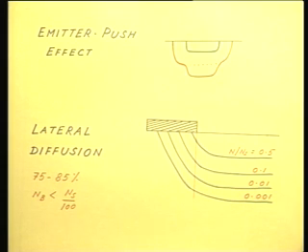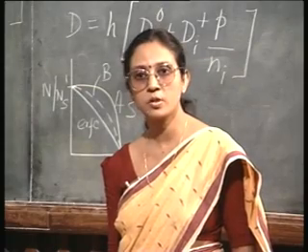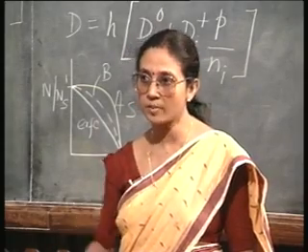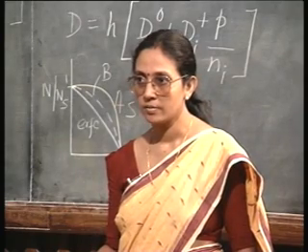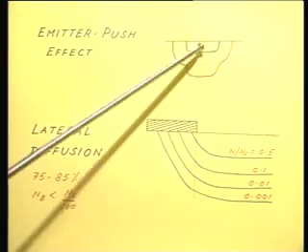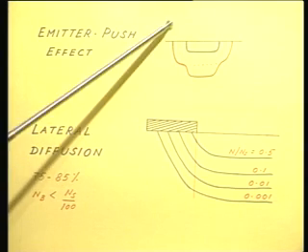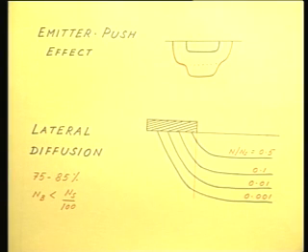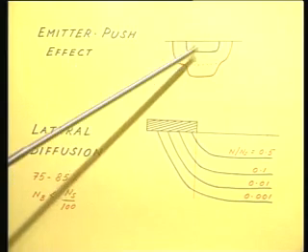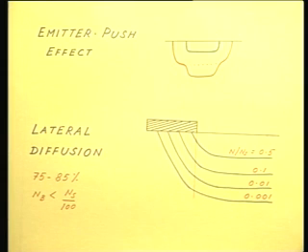What will happen to the base dopants there? They will also get diffused. Their diffusion also will get more enhanced because of the presence of these vacancies, because you know vacancies can migrate. So, just under the emitter, where the vacancy formation has taken place because of the phosphorus diffusion in silicon and the dissociation of P+V-, where all the enhanced vacancy formation has taken place, that is where you will find the base has moved in deeper.